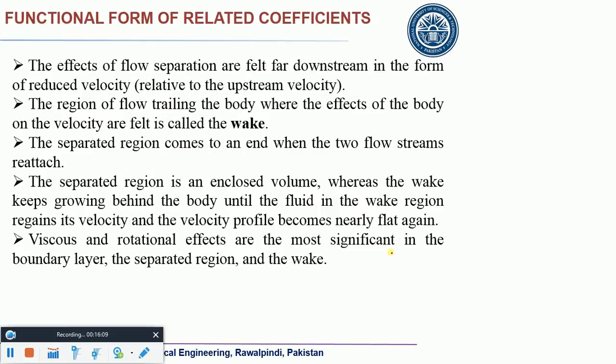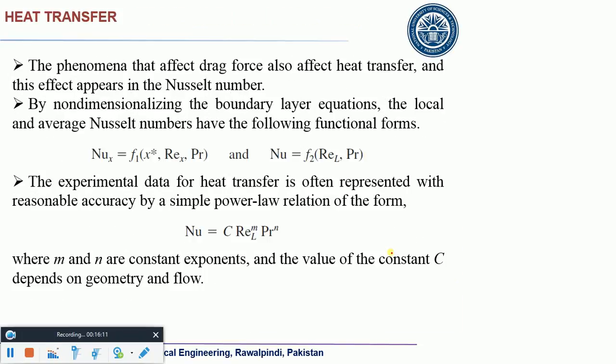You already know what is friction coefficient. Okay. You remember we talked about the relation between the friction coefficient and the Nusselt number in the last chapter. You remember that? The form of that relation was just like this. You have some constant, then you multiply it with the Reynolds number, and then you multiply it with the Prandtl number.